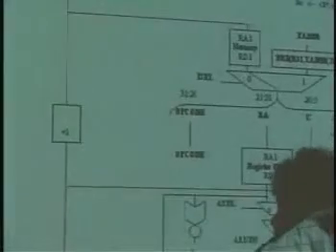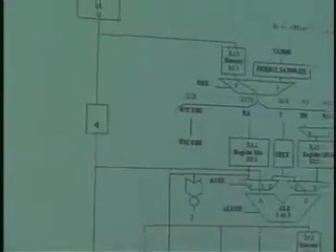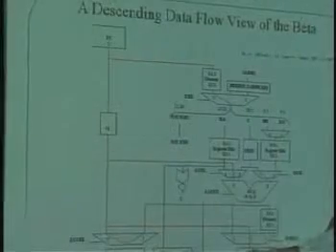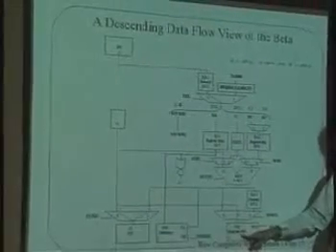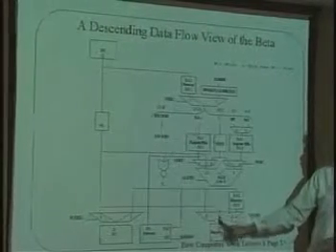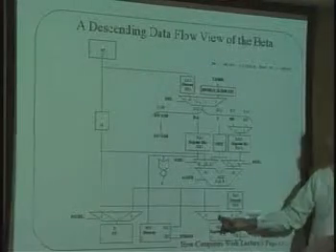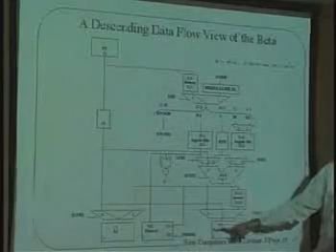And we're going to take that PC plus 1, and we're going to take this path over here that goes into this multiplexer over here. And if you remember, this guy used to be over here on the left, taking the output from the ALU and putting it into the register file. But now, what goes into the register file? The contents of the PC plus 1. We're going to choose this path here, path 1. We're going to make WDSEL be 1. And so contents of PC plus 1 will go into the right path here.